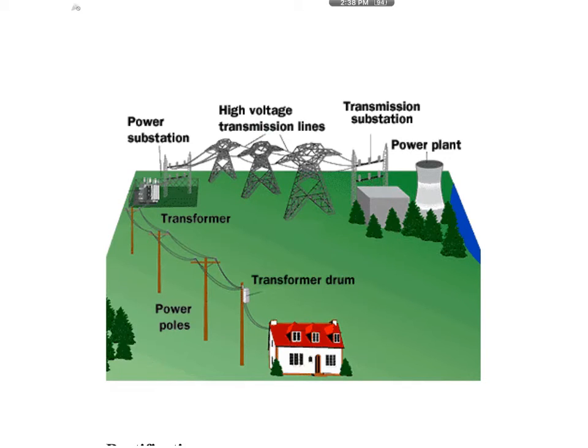The more efficient way of generating electricity is to use the exhaust gases to preheat the water, while the heat that you generate is the actual heat that you use to boil the water. So when the water turns to steam, steam is the one that turns the turbine. The exhaust gases are not wasted because they are channelled into the water to preheat it first. But this type of system takes a longer startup time because you have to boil the water first. The typical starting time is a few hours, 4 hours, then only it runs.